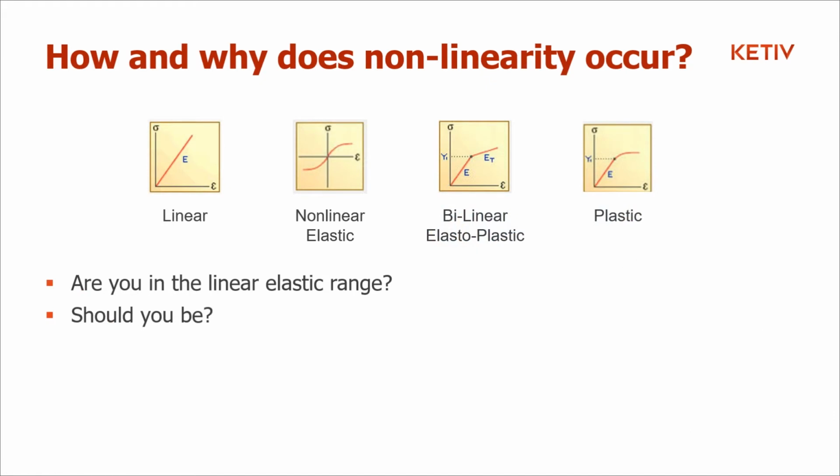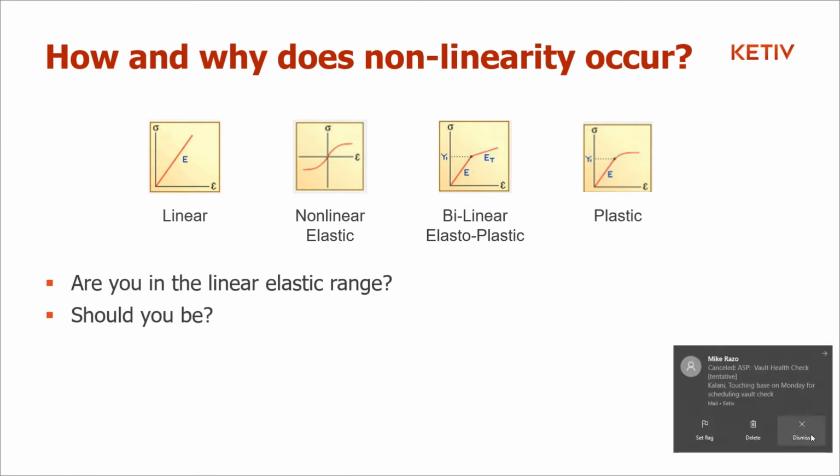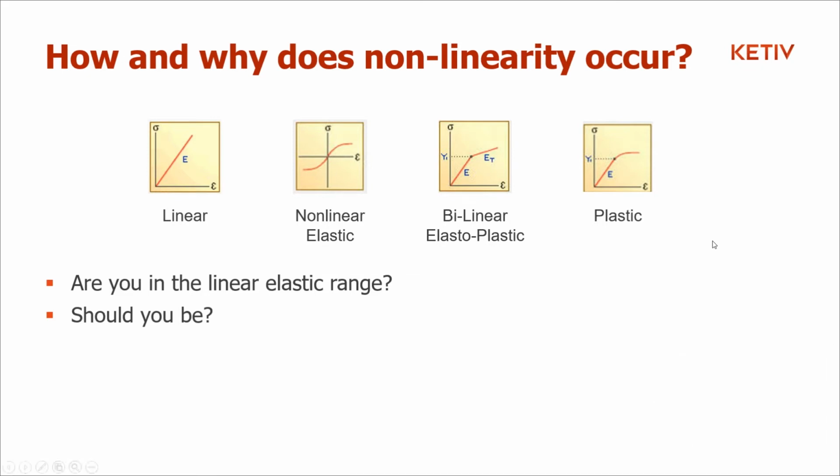The material, you want to ask yourself, are you within the linear elastic range or not? Linear, you see there on the far left, for example. Once you go beyond that point, you really start to hit the nonlinear side of things. So you might have to either look up the material within your library in Inventor, or do a little more research on that material online. Usually something like MatWeb might bring that up. And with plastic, you see it actually curves there at the end because, again, it doesn't actually break at the yield, right? It just starts to deform, really.